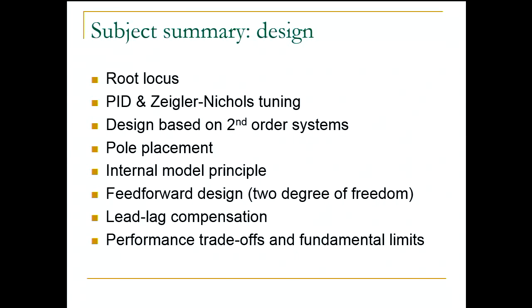And if that's the case, then a controller of degree one less than the plant dimension would do the job. So the plant has n poles, and the controller with n minus 1 poles would do the job. But we do play with all poles and zeros in the controller to achieve pole placement. And you saw the Sylvester matrix solution: the inverse of the Sylvester matrix gives you the solution to the pole placement problem.